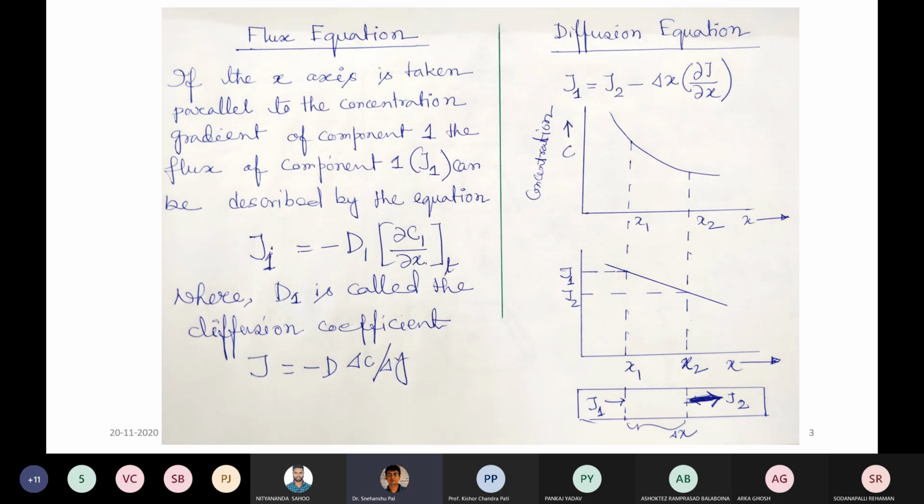Now I want to introduce one word, that is symmetry. What is that? Symmetry means whether all the directions you are interested in are symmetrical or asymmetrical. How can you understand it? If after a certain point there is repetition, any periodicity, that is one kind of symmetry. If you put an imaginary mirror in a particular plane and find the same image, and that image repeats at a certain distance, then you have symmetry. And cubic symmetry is when each unit of atomic arrangement in three dimensions looks like a cube.